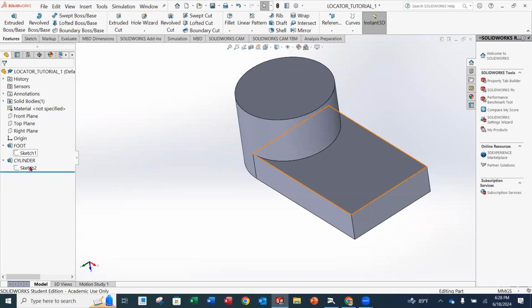And you'll notice that both of my sketches under the extrude, we're going to leave those as sketch 1 and sketch 2. And you'll notice that there isn't that parentheses with the negative sign. That means it's fully defined. Make sure these are expanded and renamed for your practice problems, okay? These are the little things that I change, if you would, as we go. And I want to make sure that you're following along.